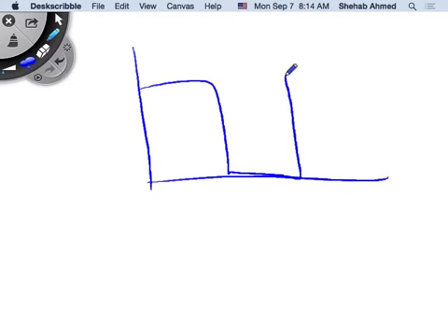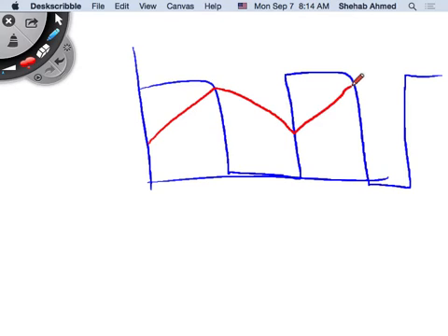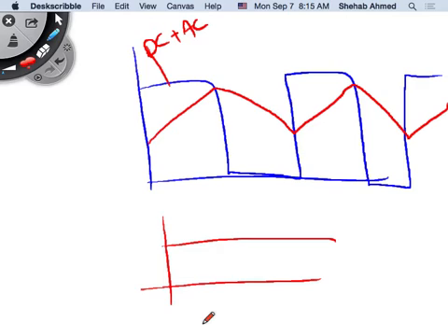So this was my waveform. And for a certain filter, I removed some of the AC component, since this has DC plus AC components, lots of AC components. So I put a filter in there so that I can remove some of the AC component. If I remove some of it, then the DC component left in there will be a lot more pronounced, along with some AC component. The AC component accounts for this ripple. If this is the DC component in the system, it is the average value of this waveform here.